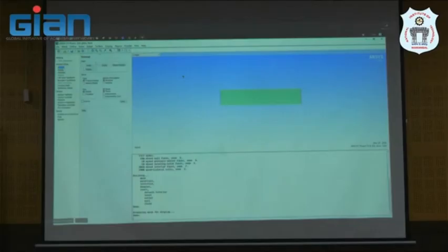Here we should change the unit, because the unit in our simulation is millimeter, so we should change to millimeter here, and so the figure is 10 millimeter long and the diameter is 2 millimeter.